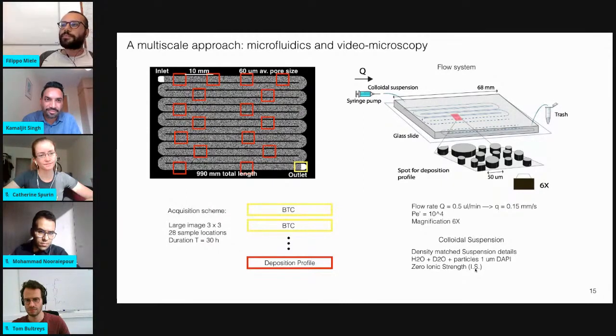So there is a limitation of the particle tracking, and in that case you have to find a good compromise between the mean velocity, which is something that you can tune with the syringe pump by imposing the flow rate, and also the concentration of the colloidal suspension. If you want to go faster, then it's better to use a low concentration. In that case, you are increasing the interparticle distance, and then you can tune the parameter where to find the best candidate between two frames.